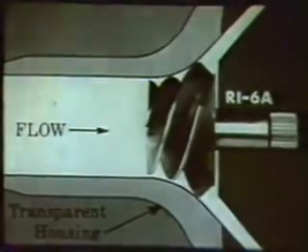At this throttle setting, a side view of the rear channel was taken at twice the speed, and for the net positive suction head corresponding to a 12% drop-off in the impeller head rise.